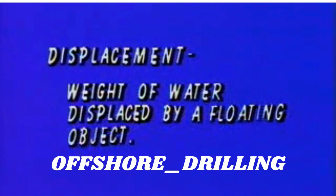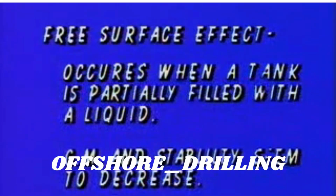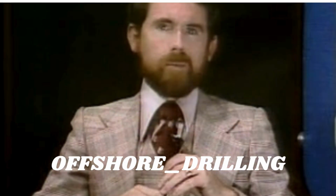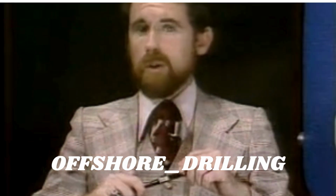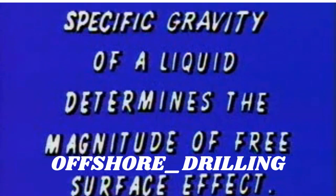Displacement is the weight of water displaced by a floating object. It is equal to the weight of the object itself. Free surface effect occurs when a vessel has partially filled tanks. The effect is such that it causes a decrease in metacentric height, GM, and a consequent reduction in stability. The wider the tank, the greater the free surface effect. The greater the displacement of the vessel involved, the less the effect of free surface upon stability. The specific gravity of the liquid in question will also have an effect on the magnitude of the free surface effect.